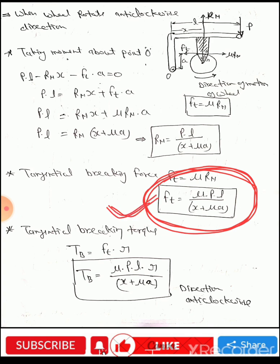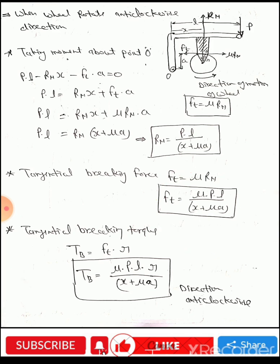This is the tangential braking force. Now we can also obtain the tangential braking torque TB. This is equal to the tangential braking force times the perpendicular length, or radius of drum or radius of wheel. So TB is equal to Ft into r. Here small r is equal to the radius of wheel.